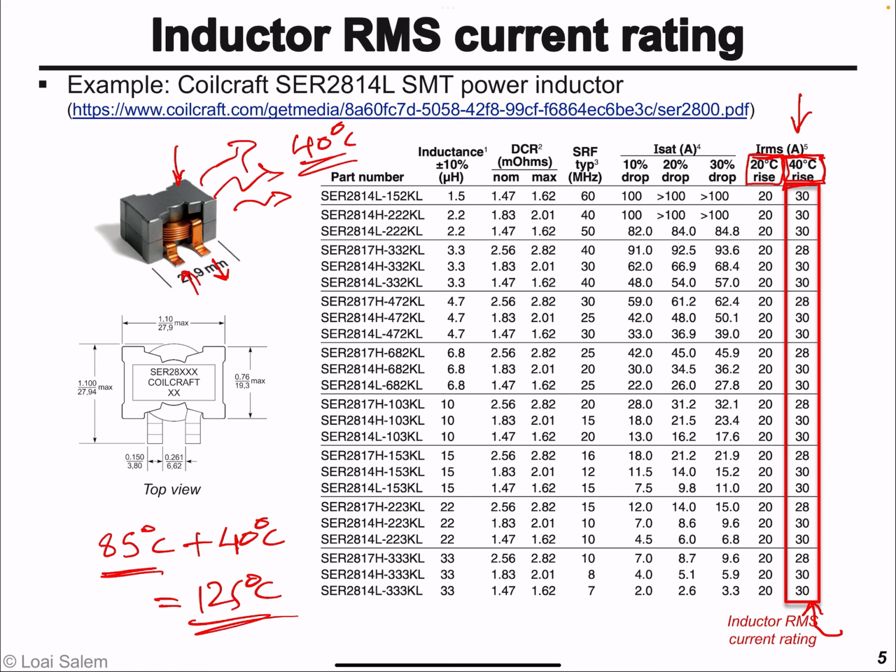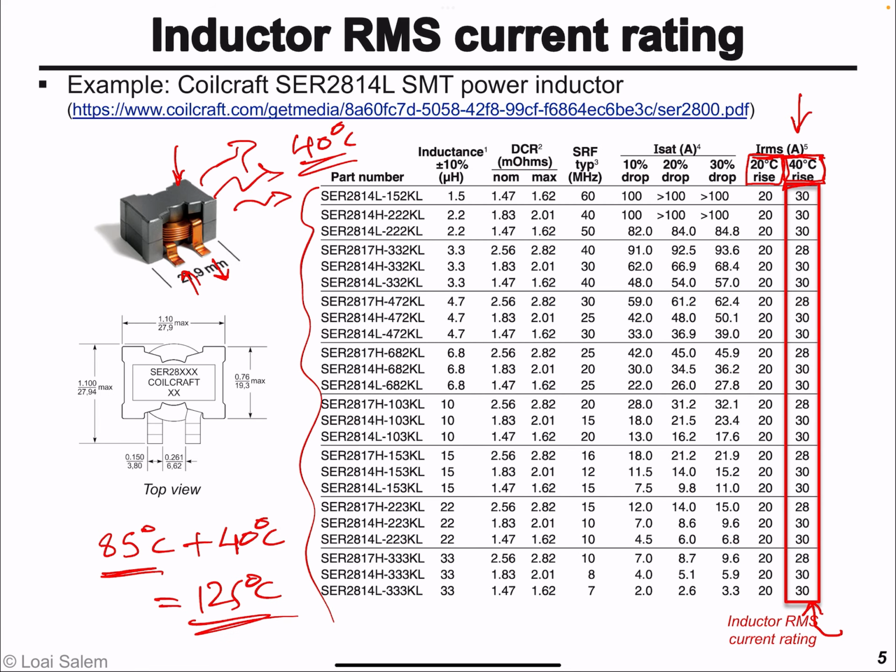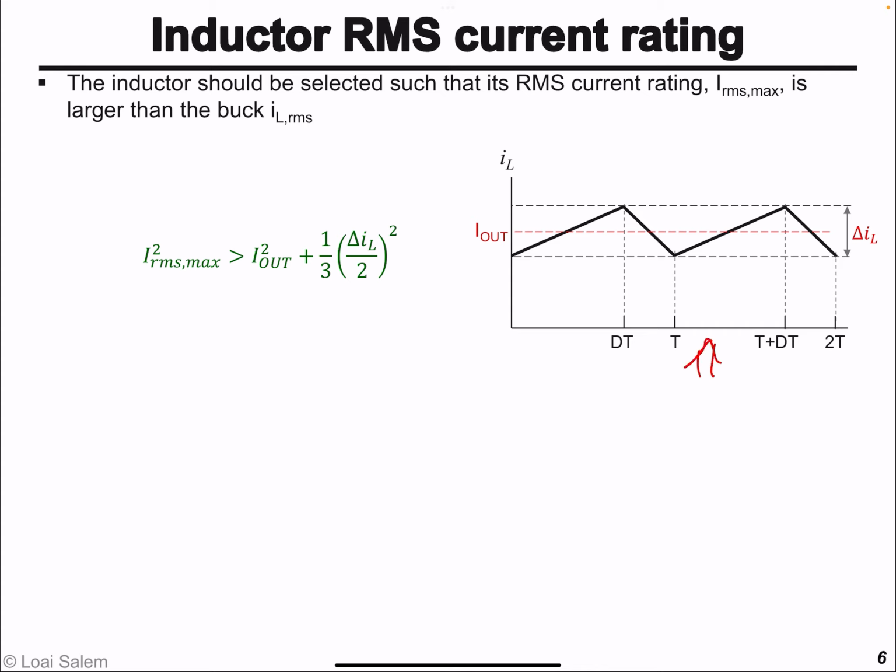And of course, whenever we select an inductor with a certain inductance, we need to make sure that this inductor will be able to handle the high currents of the buck converter we are designing. And so we need to calculate the RMS value of the current flowing into the inductor. As I mentioned before, the current of an inductor has a triangular waveform, essentially a triangular periodic signal superimposed on a DC component. If we separate both, we have a DC component and then high order harmonics.